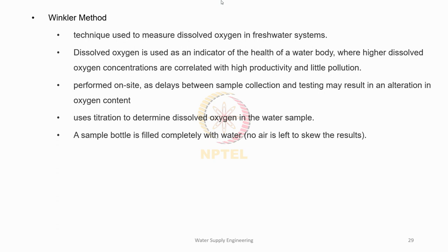So it should be rinsed thoroughly with that particular sample water itself, and then it is filled completely with water. That is, we should ensure that there is no air left, otherwise some error may come up in the result. Because if some amount of air is already there, that will give us an erroneous result.